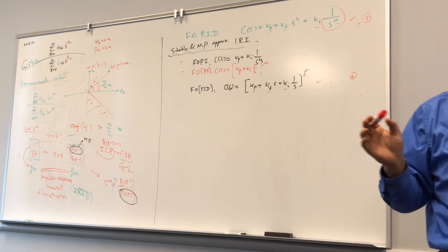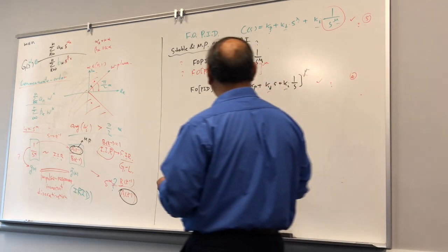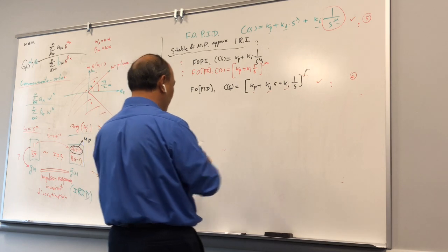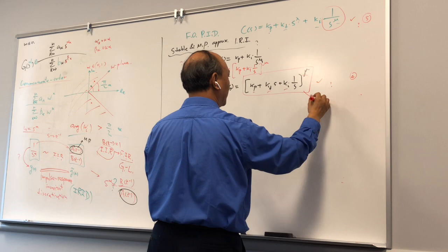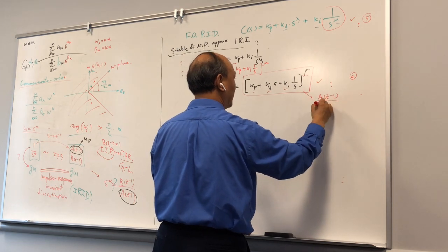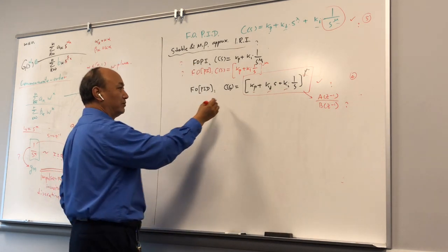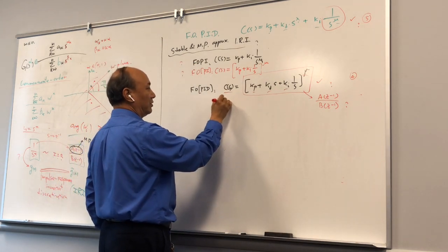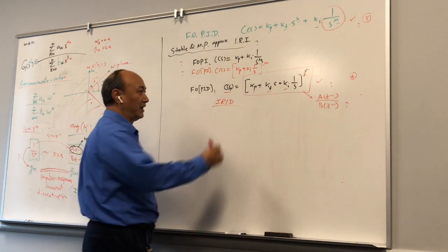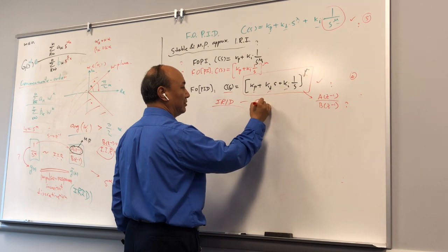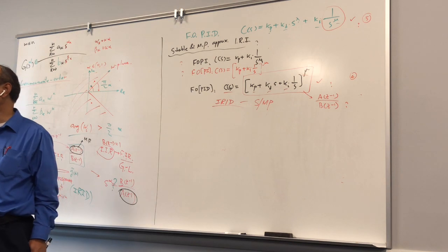Yeah. We haven't written this paper yet, so you have opportunities here. But now, the question is, given this one, how can you approximate it into A(z^-1) and B(z^-1)? How? And still, I hope this is an impulse response invariant discretization, and I hope it is stable and minimum phase. Okay? Stable and minimum phase.